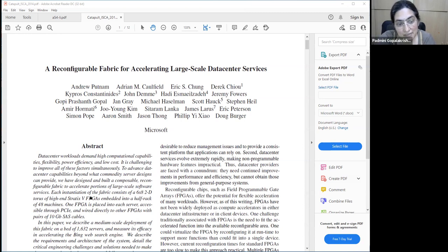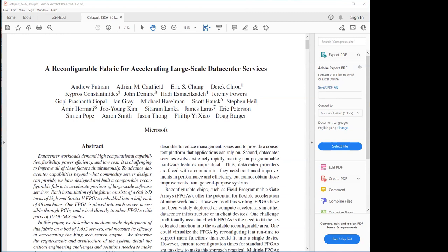But it is important, when you're actually building an overlay, to also think about the system-level specs. How will this actually be used in a system? If you are putting that overlay on a single FPGA, you need to keep space to store data if you need to store it. You need to understand the system-level requirements when building something. Did that answer your question, Diksha? Yes, ma'am. It's a good point.